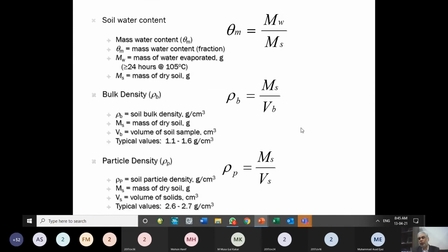With respect to that, you should know how to convert this moisture content into depth of water, because we are familiar with measuring the volume of water in cubic meter units or in depth of water units. If you know how much depth of water is required, you can convert it into volume by multiplying with the area on which that depth is applied. And if you have the volume of water available, you can convert it to depth by dividing by the area on which you want to apply that volume of water. So to convert moisture content, theta, into depth of water, we need a formula.